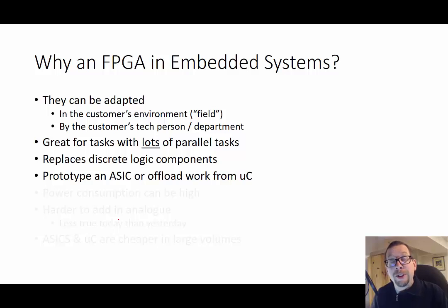Engineers often use FPGAs as they go towards application-specific ICs or ASICs. So an ASIC, when you design it and then manufacture it, can be really expensive. And in the process to get to that point, you often want to have a system that you can prototype and change and adapt and show your boss, and FPGAs are very good for that because they're relatively low cost when you compare it to the actual development of the ASIC.